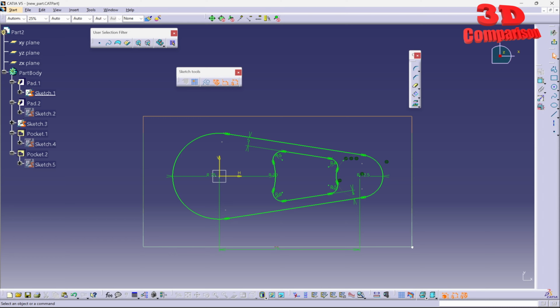So let's see. I also created the same part, and over here, as we can see, we have the seam line of that cylinder aligned differently. If I enter this sketch, this has been designed like this. So top down, we see the Y and X axis. And in this case, the pad will be like this. So again, Y and X. And that means that the seam line for the extrude circle will be over here. And that will not influence the edge fillet.